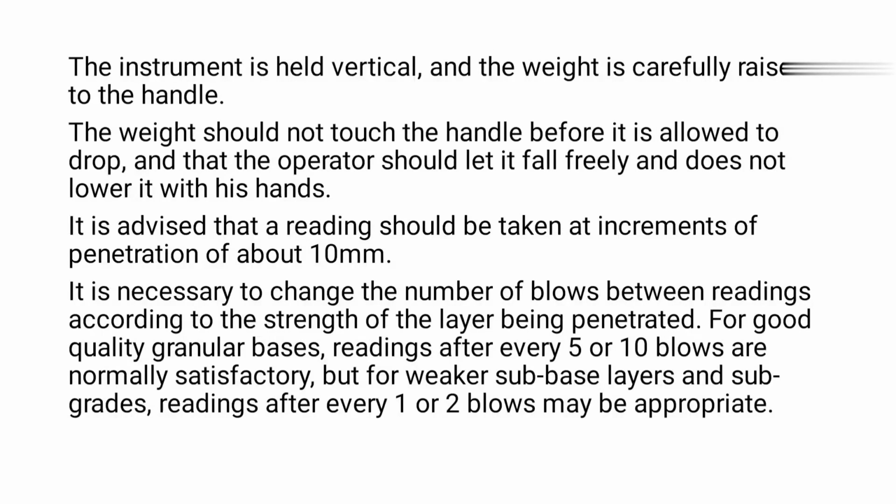First of all, the instrument is held vertically and the weight is raised carefully and allowed to free fall. Due to the different strata, the number of blows between the strata varies and is to be recorded. It is advised to take the reading as an increment of about 10 mm penetration. For good quality granular bases, the reading is for about 5 or 10 blows. For loose, that is weak soil, readings of 1 or 2 blows may be appropriate.